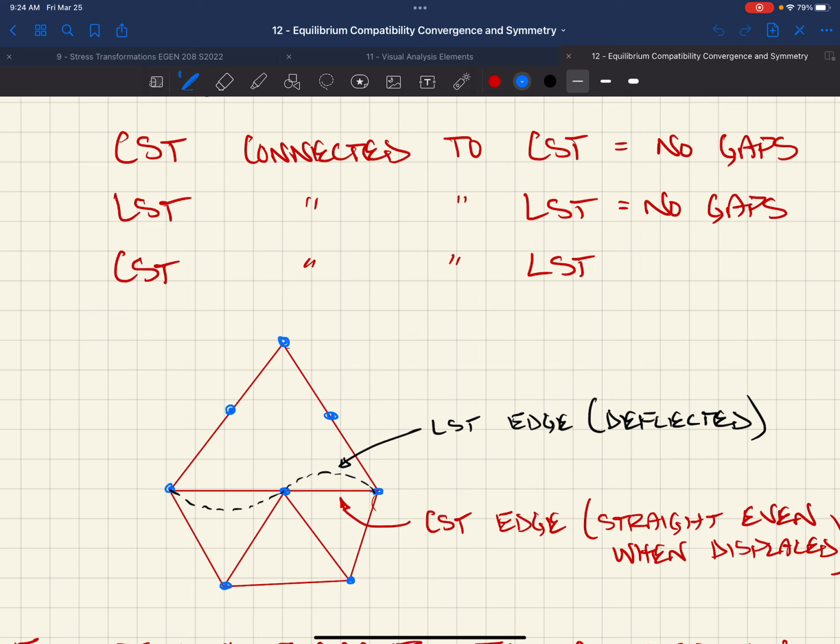I had a hole in our plate, and I had a pin, and that pin was putting force on, say, this larger element. And I wanted to make sure that we captured that behavior right here, in the fact that this is only going to press on, it's not connected, but it can push on it, okay? But out here, I'm going to be looking at other things. So you want to make sure that you take into consideration what you're trying to get out of it, and then also how that's going to affect your results between these elements, what's going on.